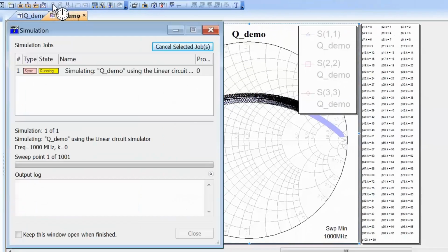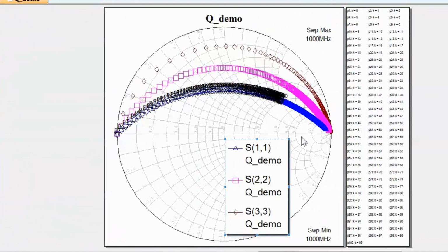Now let's simulate. Now you can see that the arches increase in height as the Q is increased. So we are effectively describing this sort of lines on the Smith chart as we look at impedances with identical Q, and these arches, these lines, tend to go higher and higher as the Q of the impedances gets higher.